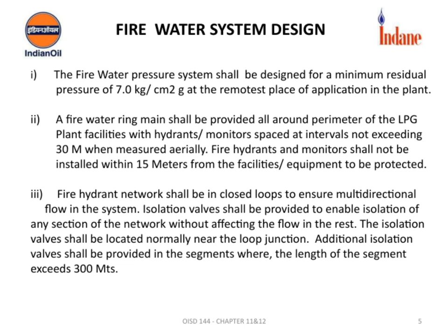Additionally, in segments where the pipeline length exceeds 300 meters, extra isolation valves should be installed. This helps manage flow and maintain pressure across longer distances, ensuring that the entire system remains operational and effective during a fire. Overall, these design principles are vital for creating a robust, reliable fire water system that can respond efficiently in emergency situations, supporting safety across the entire LPG plant.